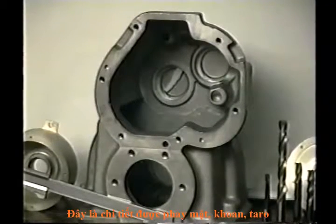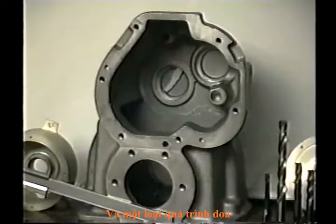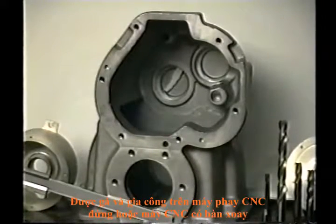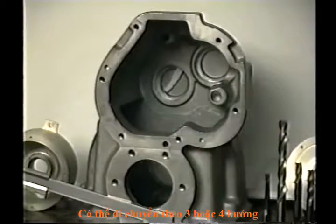Here's a part requiring face milling, again drilling, tapping, a number of boring operations, and this part has 3 sides that are actually machined, so it would require fixturing on a vertical machining center, and possibly on a horizontal machining center it could be sitting on a turntable actually turning itself around, so we could work from 3 different or 4 different directions.